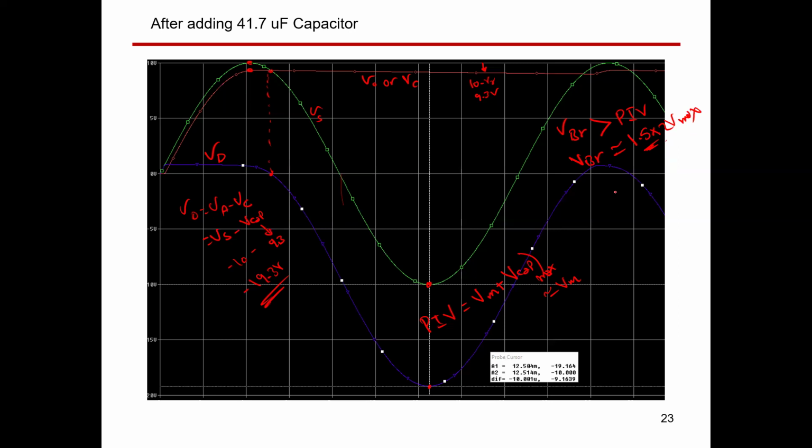But what about the capacitor volt? Actually, as you can see here, the capacitor volt is going to be rated at V maximum of your supply. So if your supply volt is 10 volt, the capacitor volt is going to be 10 volt at most. But again, you should consider some safety factors. So select the capacitor volt to be, for instance, 20 volt. You may not find a 15 volt capacitor, okay?